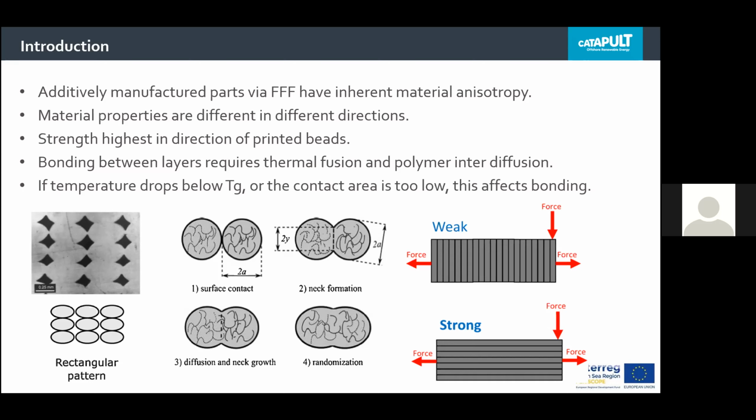So for the interlayer, the bead needs to be maintained at or around, or preferably above, the glass transition temperature to be able to get a good surface contact area. So the strength transferred to the beads is derived from this contact, the formation and the coalescence of beads.